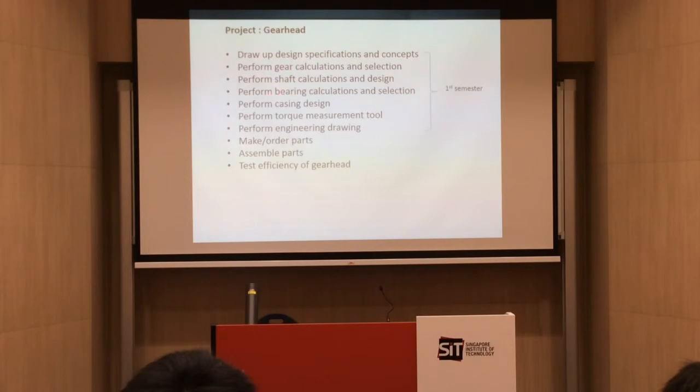And then once you get your gears, you have to calculate the size of your shaft. Because every gear has an inner bore that fits the gear to your shaft. And the shaft, you have to make sure that it doesn't break. Because if you select too small a size, then it will break. So you have to do calculations of your shaft. And once you determine the minimum size of your shaft, then you can start thinking about selecting the bearing, to make sure that the bearing fits your shaft.